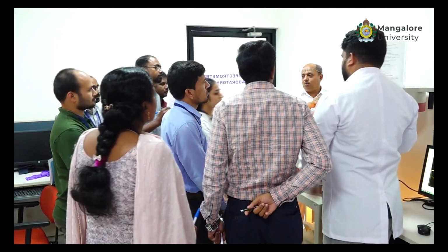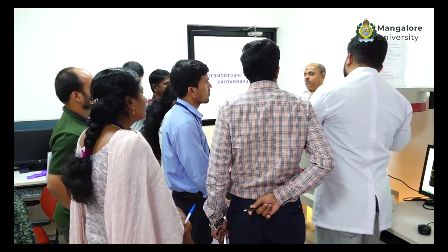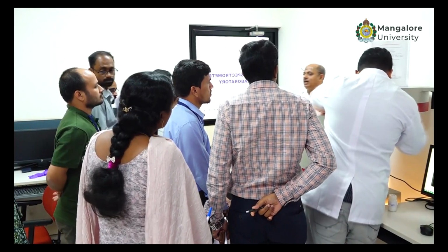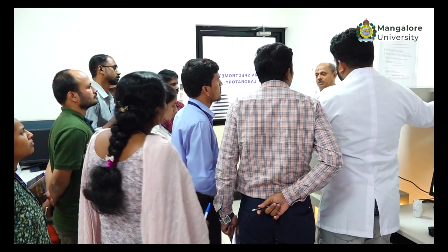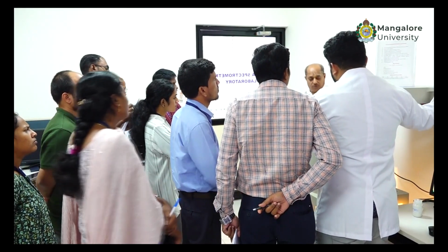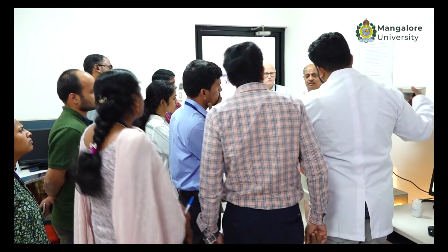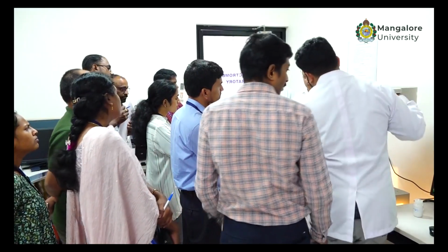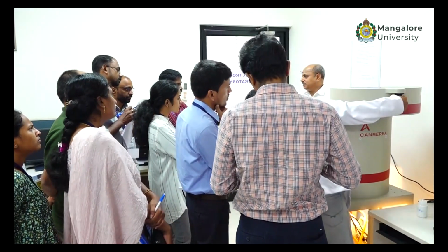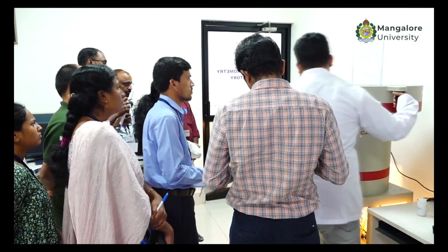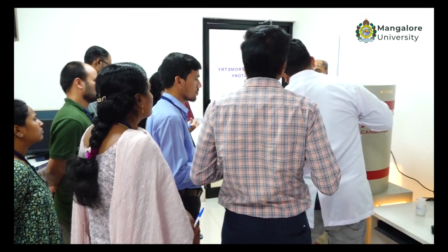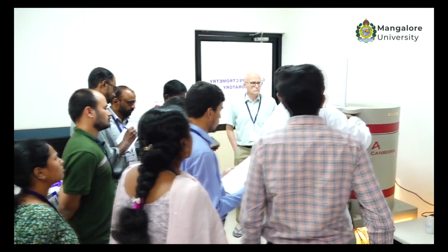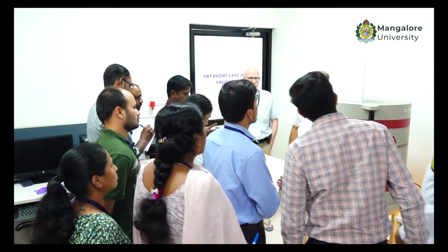In our case it is a composite carbon. There could be beryllium window and aluminium window. We use composite carbon because composite carbon is a better material which allows both low energy as well as high energy gammas. So that's the reason for the composite, and this composite carbon material is very sturdy.